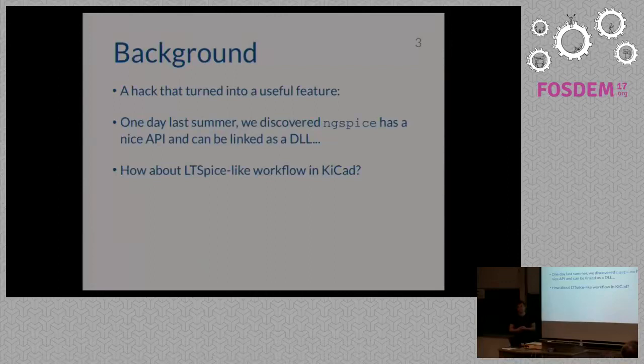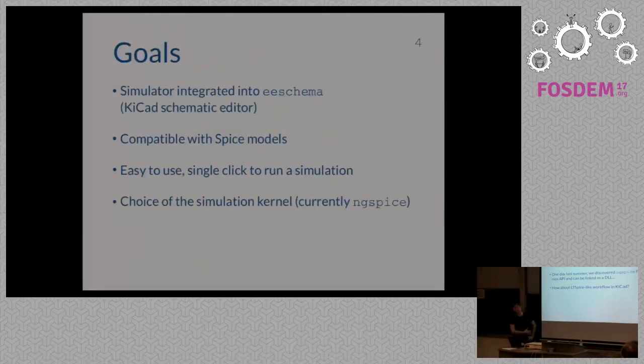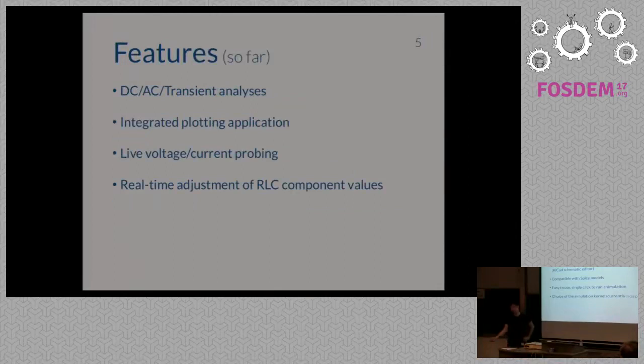And our aim was, why don't we try making something that looks and feels a bit like the non-free but industry standard LTSpice, but in KiCad. So our goals were to have a simulator integrated into Eeschema, which is the fancy name for the KiCad schematic editor, that is compatible with SPICE models, that is reasonably easy to use, ideally one click to run a simulation, and that in the longer run allows for the choice of the simulation kernel. Currently we support only ngSpice, but this will likely change in the future.